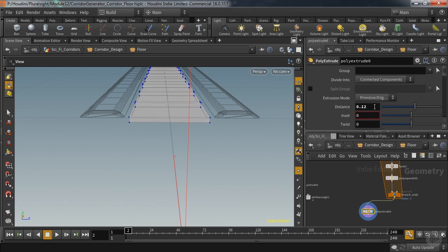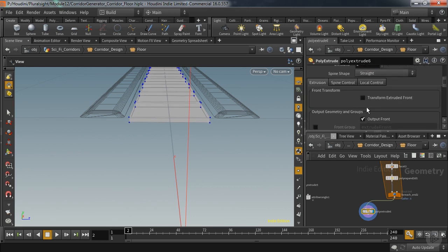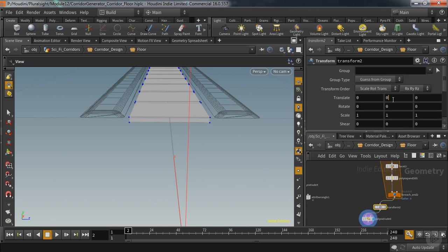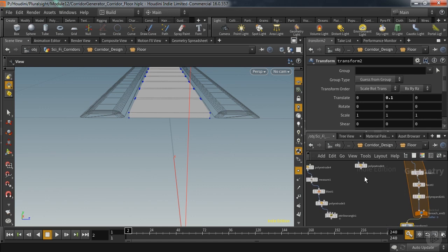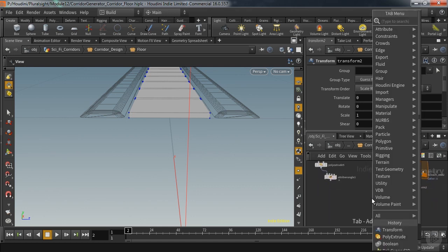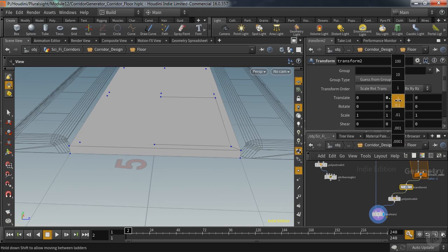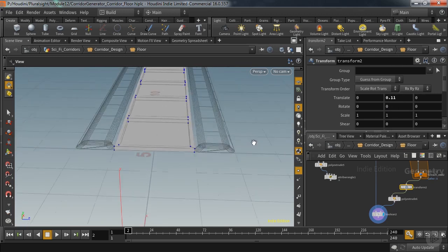In addition to that, we will most probably need a transform node to adjust the height of the stencil in relation to the block. So place the node and let's start by bringing it to its original position. Then grab the block and create the boolean node I was talking about. Then connect the prepared shapes into the second input and set the operation to union. I eyeballed the position of the shapes, so you might need to return to the transform node and adjust the position. And with that, the block is prepared, we have the cavities to hold the grates.